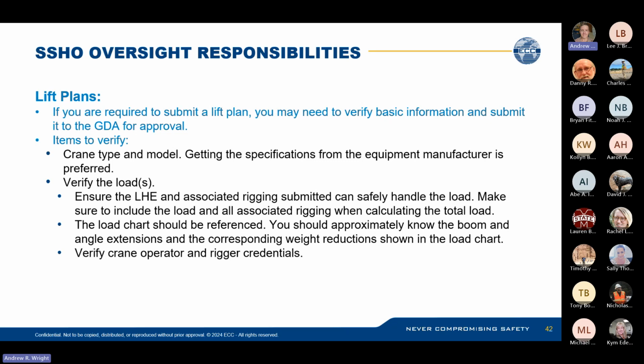The load chart should be referenced. So you should approximately know where the boom and angle extensions and the corresponding weight reductions are going to be shown in the load chart.